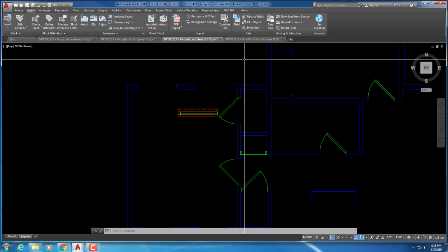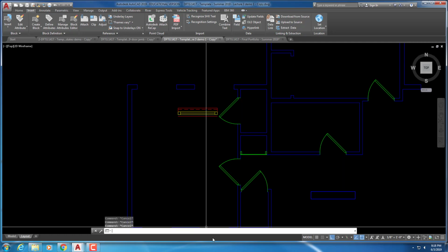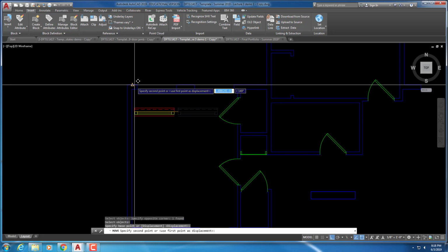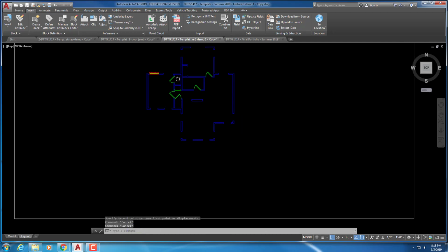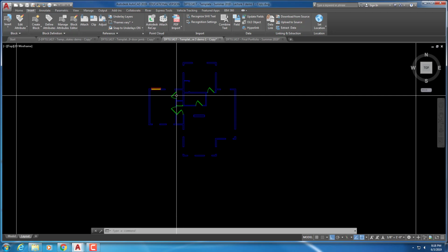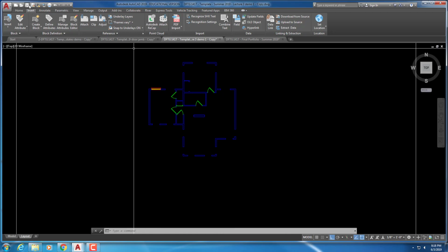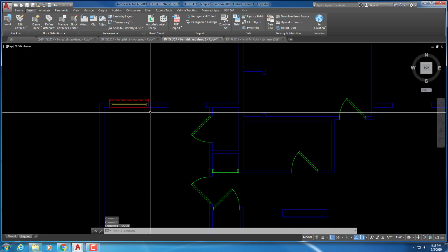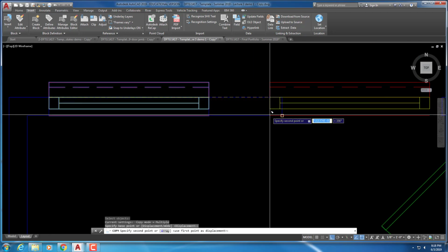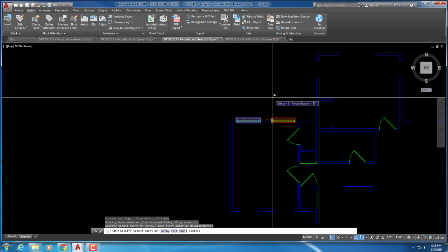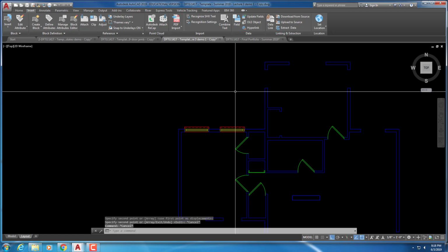If you don't do that, you'll obliterate your first floor block, or you won't get it to show up for your second floor block. But once you've done that, you can use that block, which is now a new block based on the second floor layers, and they did the same thing we did on the first floor. And then you would also add your siding, the 3 inches out on the A2 wall siding layer.